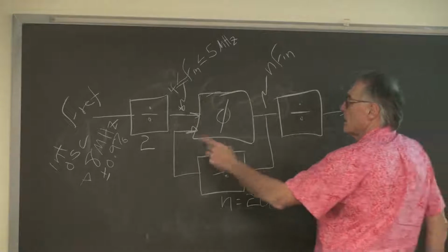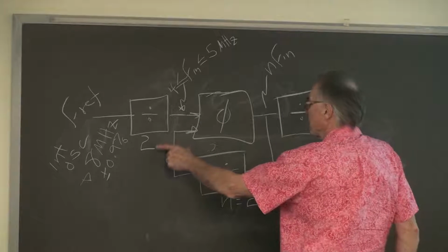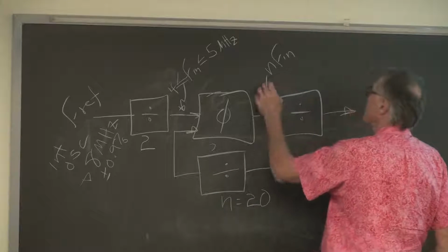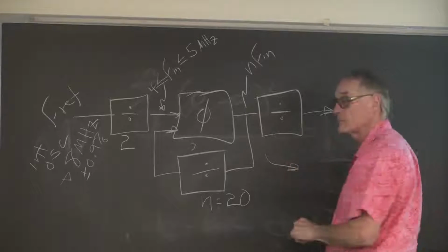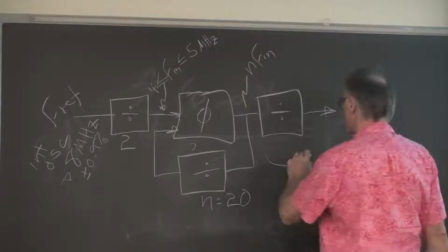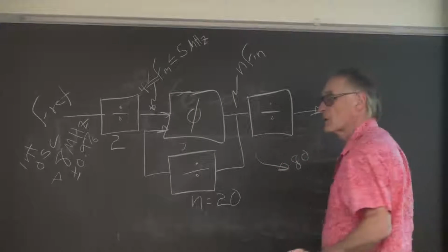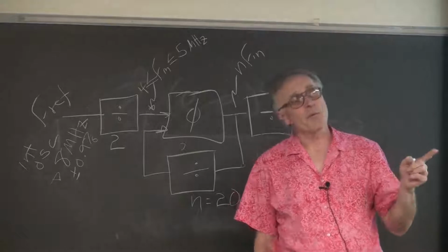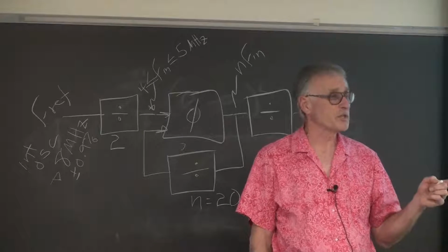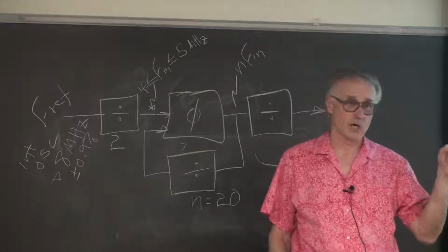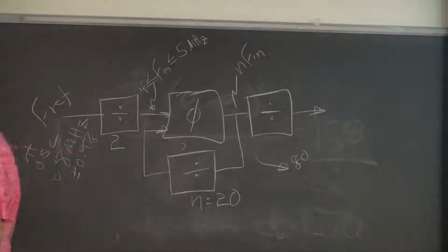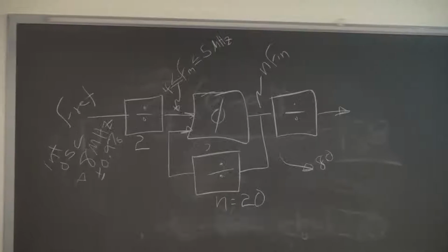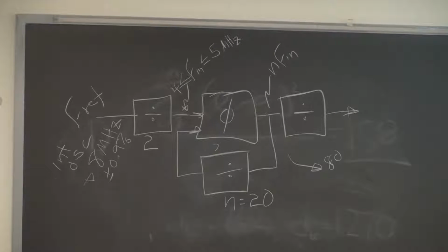So for an 8 megahertz signal divided by 2 times 20, the output here would be, if n is 20, 80 megahertz. That's above the maximum operating frequency for this chip. This chip is rated at 50 megahertz. You can actually look at that on the chip itself. It gives the part number, and then there's a P50 afterwards, which is 50 megahertz.